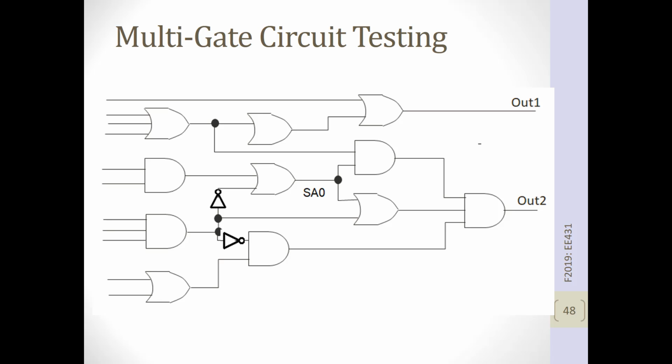So far you've been doing an exhaustive test of a combinational logic circuit. And remember how you set stuck-at faults around each gate, and then if there were two on the same wire that were the same, then you could cross one out, et cetera, and you got down to a smaller set of test inputs to exhaustively test your circuit.